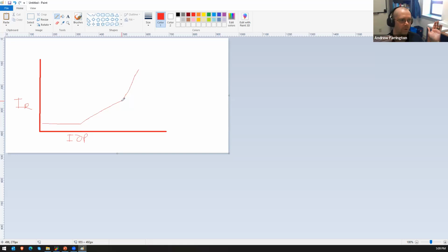Well, then when you go to 1 raise or 1 lower, say you've changed the turns ratio of the transformer, and now you've got a little bit of operate current. So you can have LTC differences that you need to account for. And then up here is the nonlinear restraint, or nonlinear slope, I should say. So this would be for preventing misoperations due to things like CT saturation. But in essence, it's very similar to the concept that Brandon went over for bus differential relaying.